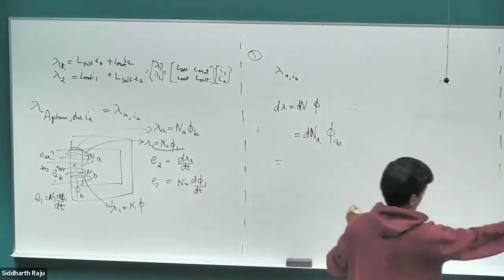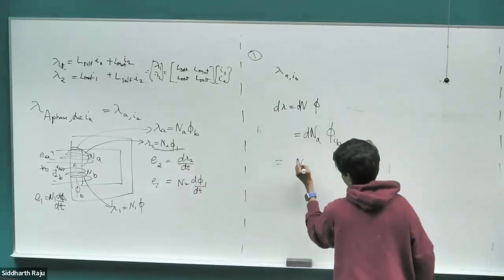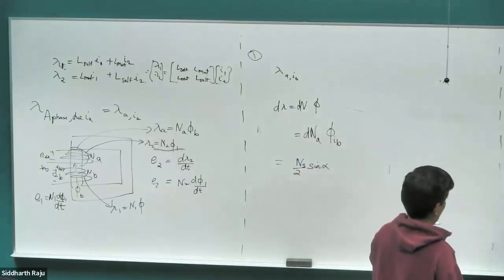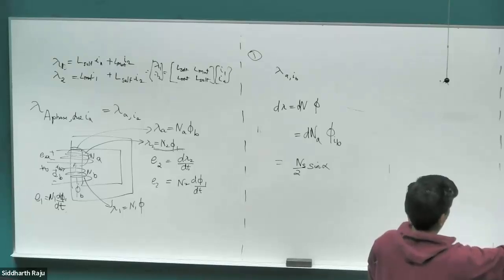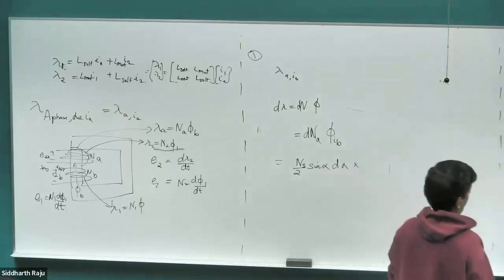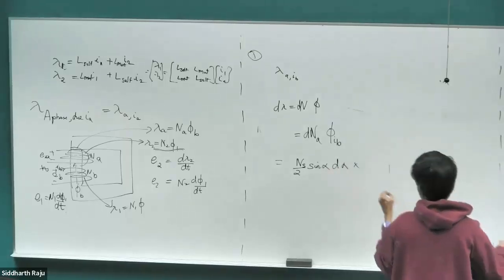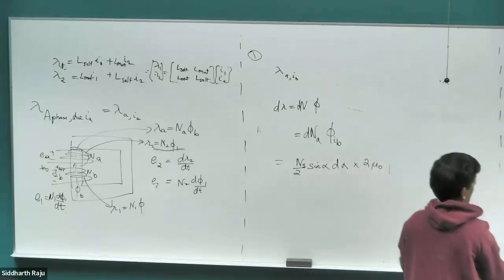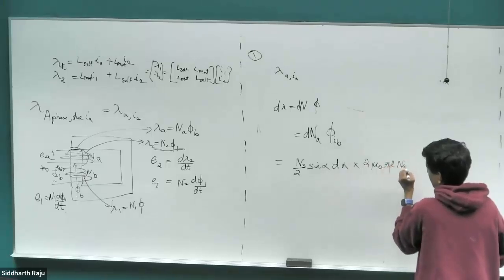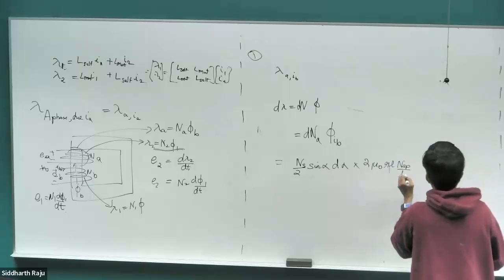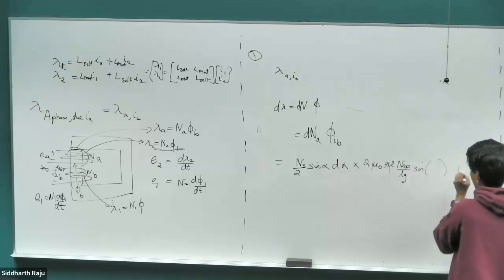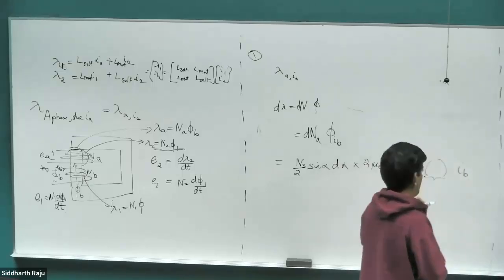Okay. So in that expression, everything remains the same for the first part. So it is n divided by 2 sine of alpha. That part doesn't change on the top equation. I'm going to leave out the p by 2, just looking at the 2-pole case for continuity. And then the second portion, 2 times mu naught RL NSP divided by LG, times sine of something times phi d. What would this be?